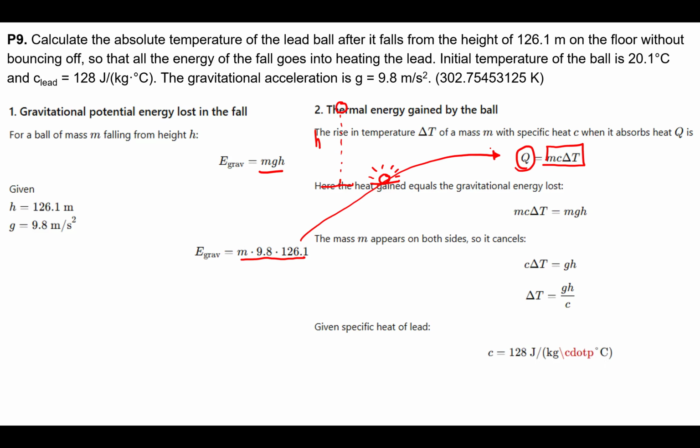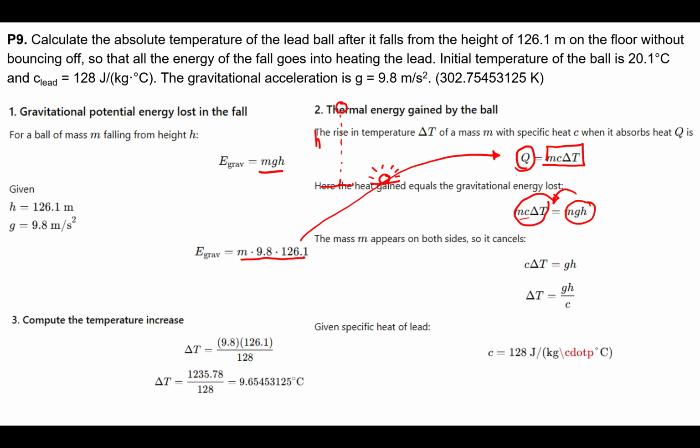So the first thing is that the heat transfer Q is in fact energy, joules, right? So in this case, the potential energy of this ball is now changed into heat. And then we can find out the delta T, and you can get the delta T like this.